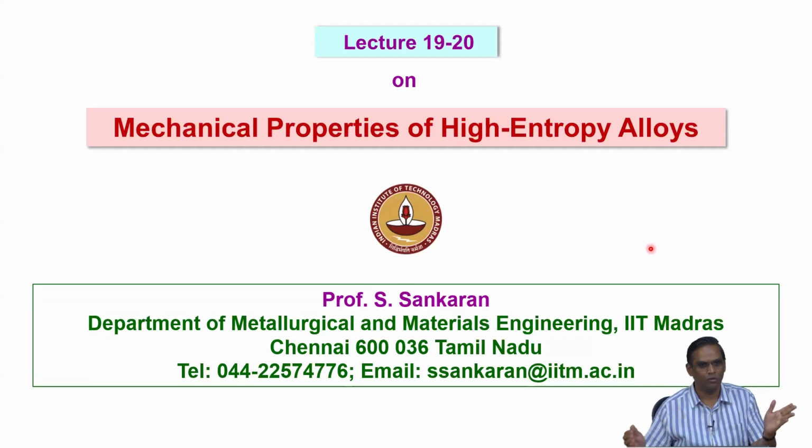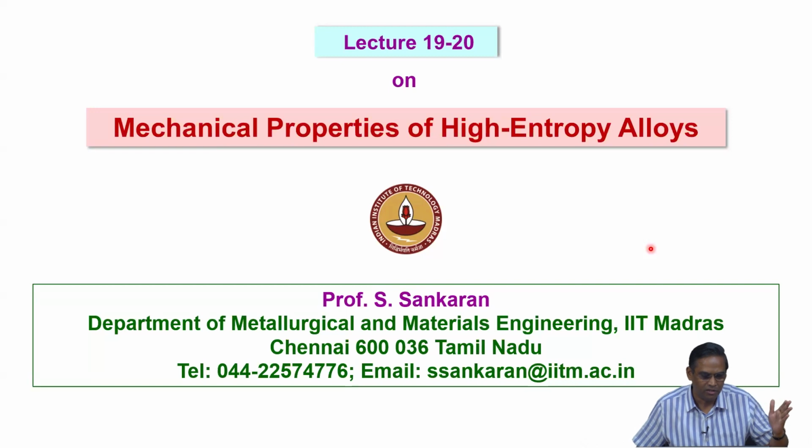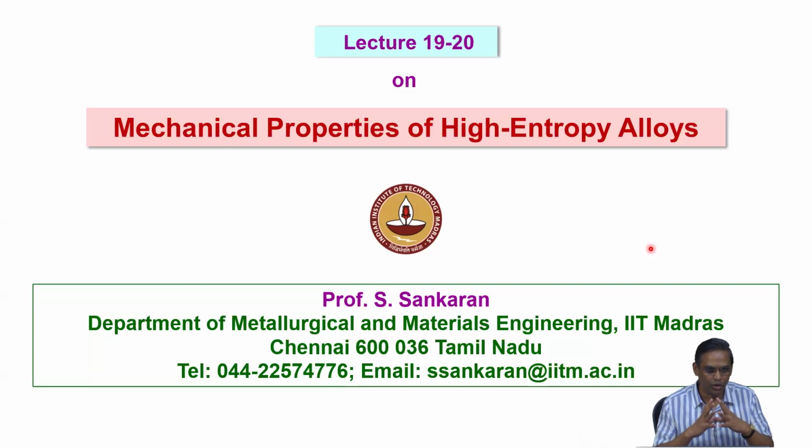And then also we know the popularly known stacking fault, right? So when you look at the broad classification of materials, you have the materials which during deformation exhibit a wavy slip or a planar slip. So this classification stems from the concept of the stacking fault energy.